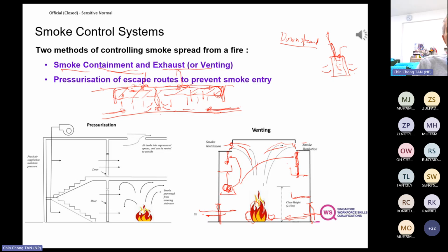It can be very frightening, because when the smoke curtain drops, it's very noisy, lah. Huh? And especially for children, they may not know what's going on. So this you still can go in, okay. So the smoke curtain is to prevent smoke from going into the occupied areas. The other reason is for it to create a reservoir, like here, okay. Create an upper layer, hot upper layer, so that the fan will have some volume of smoke to suck up, to draw out, okay. So two reasons: prevent smoke from going into occupied areas, and also to create a smoke reservoir, okay?